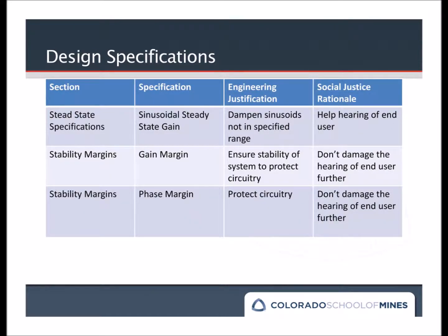The design specifications for this project were chosen to create a stable, pleasant experience for the end user. Our steady-state specification was to amplify any sinusoidal inputs within the passband of the filter while attenuating all other frequencies. Because stability was an important consideration for this system, our other two design specifications involve gain and phase margins.